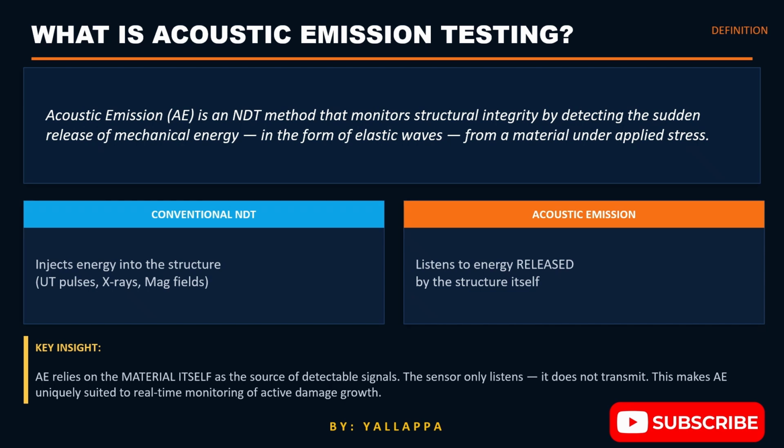The story of structural health monitoring. But remember one important limitation. AE can locate active damage, but it cannot accurately size the defect. For sizing, we still need supplemental methods like UT or RT. Very important Level 3 concept.